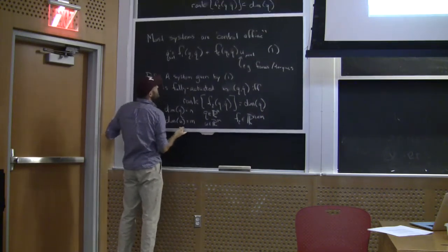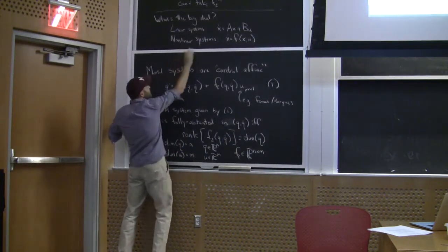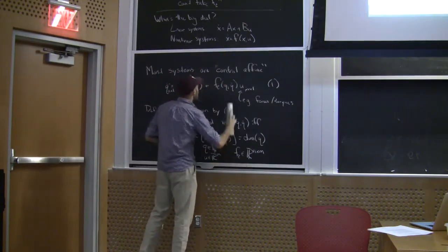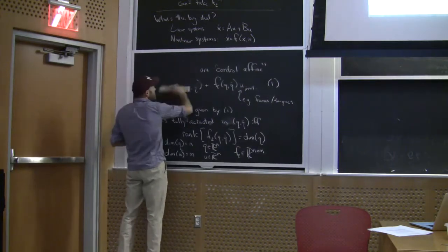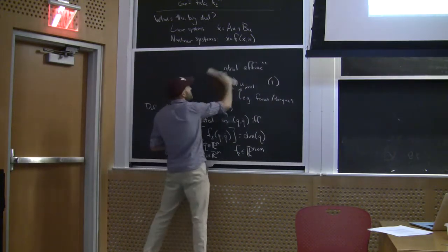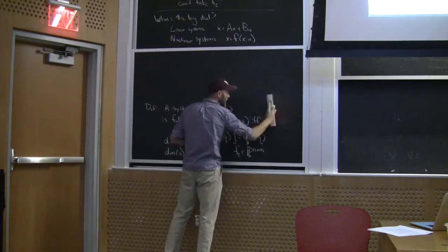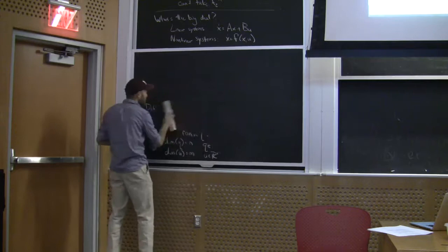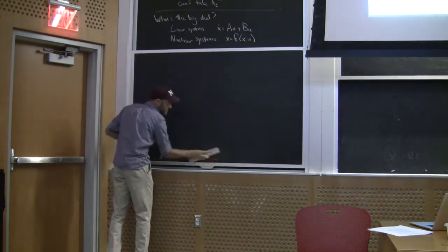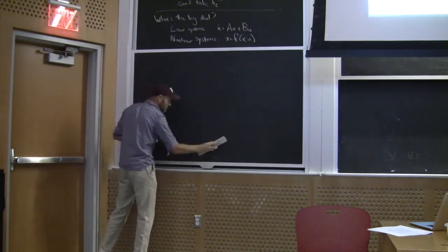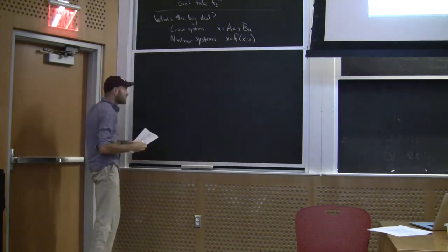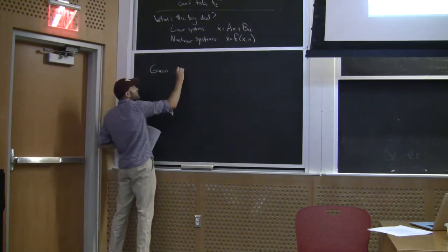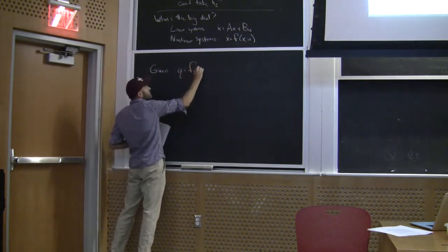All right, so here's the trick. Almost all my robots in the world have some nonlinear terms f, but if they're fully actuated, then I claim that they're easy to control, and maybe you can see why, right? So if I'm given my Q double dot, my second order system form,